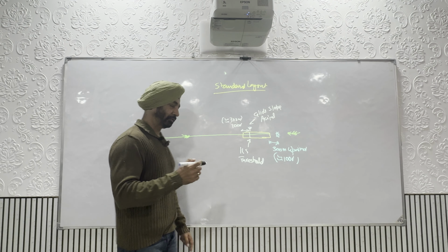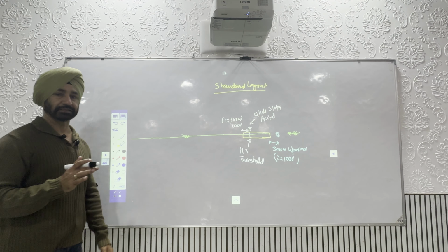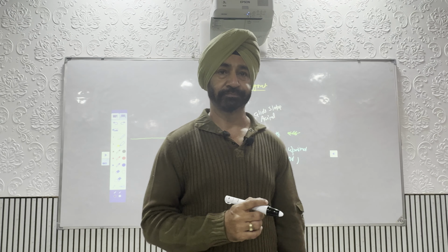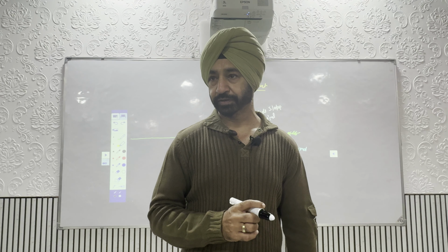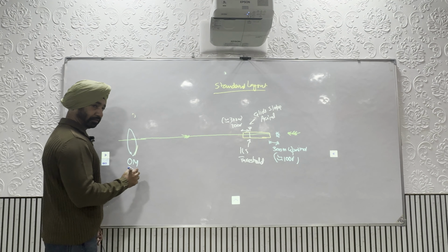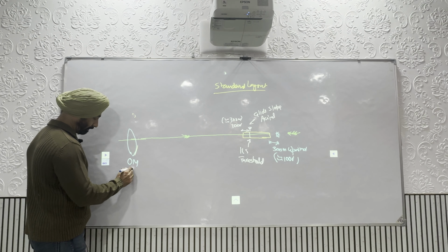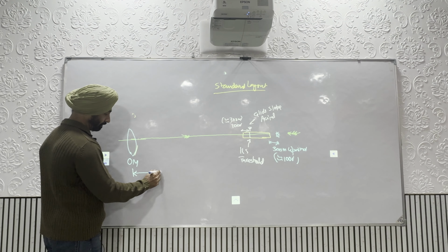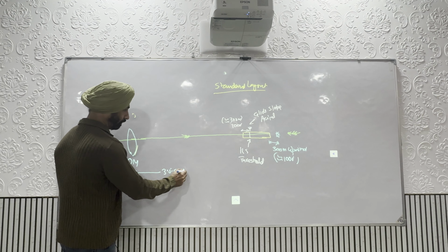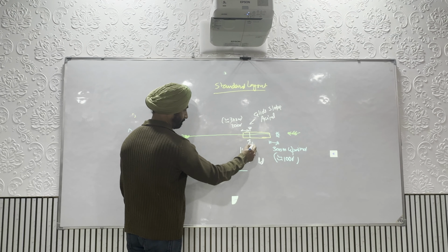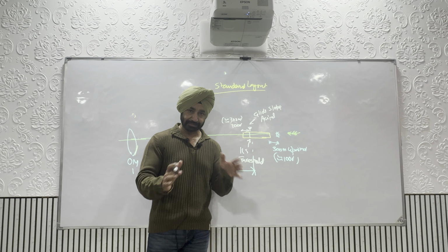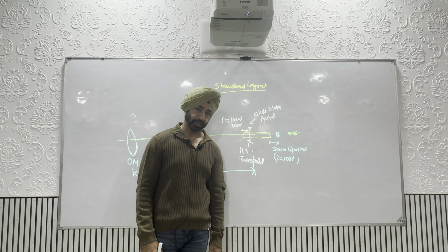Now the marker beacon distance, practically when you fly, is given on the charts. It is always there on the charts. For the outer marker, the distance from the ILS threshold recommended is 3.5 to 6 nautical miles. It may vary, but whatever the distance is, it is given on the chart.